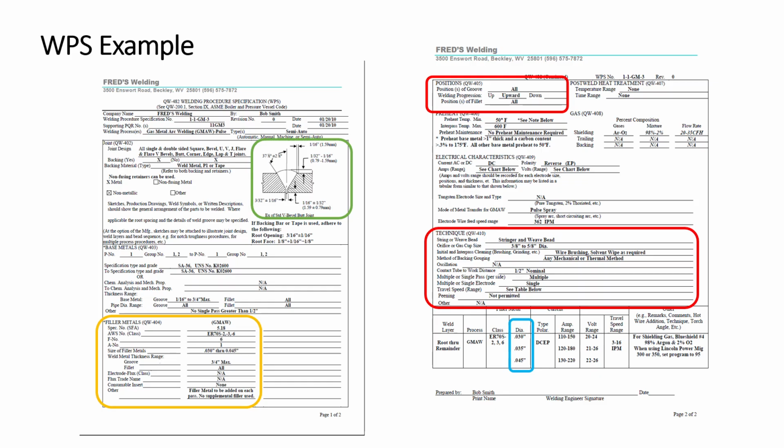but that's a story for another day. So here would be some examples of things that we would address. In that green square up there, example of a bevel weld. When I write a WPS, I might put in one example of a bevel weld, and then I'll put in some kind of wiggle words that say that we can use sketches or production drawings, or where we can use something else, that can be on a router. We've addressed it, but we're just leaving ourselves an opening, so we're not just tied to what's here.